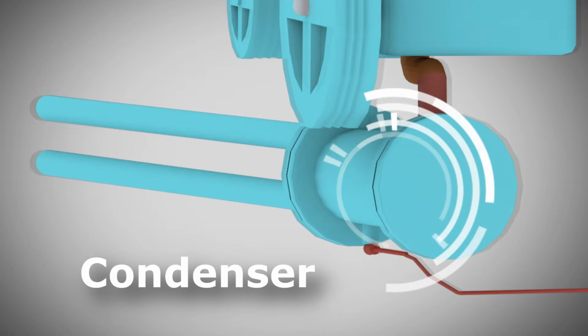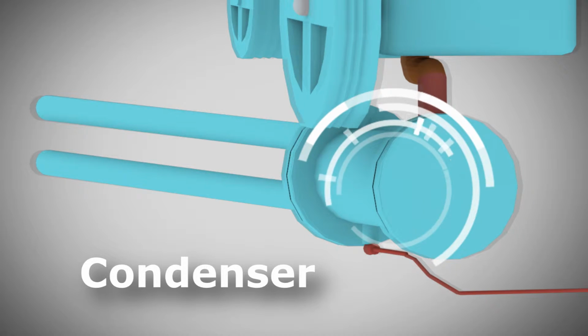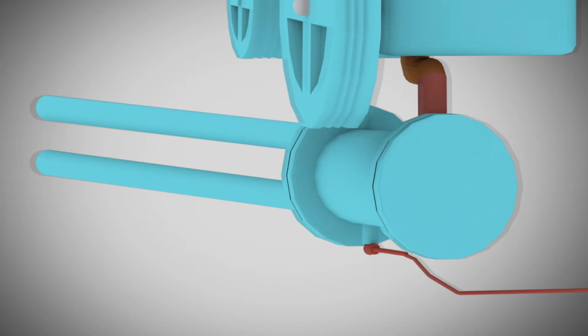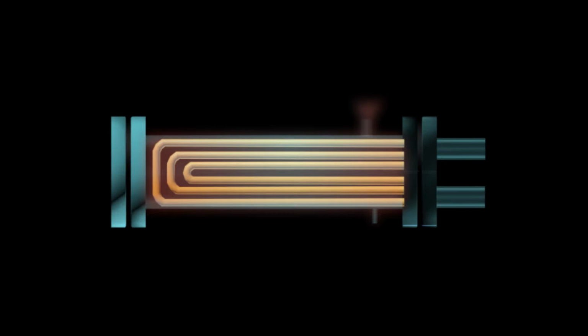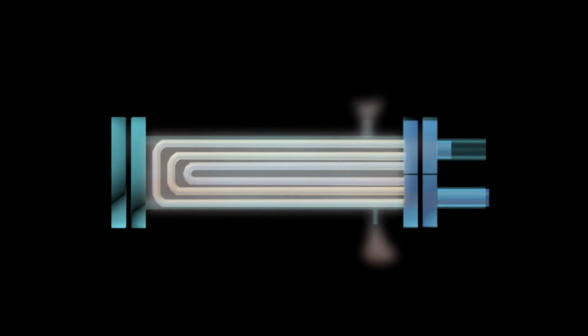Condenser. Condenser tubes provide heat transfer surfaces in which heat from the hot refrigerant on the outside of the tubes passes through the walls of the tubes to the cooling water inside. The refrigerant vapor is cooled first to the saturation point, then to the liquid state. The condensation process will lower the temperature of the refrigerant but keeping the high pressure of liquefied refrigerant.